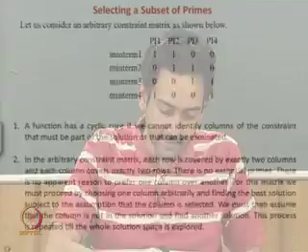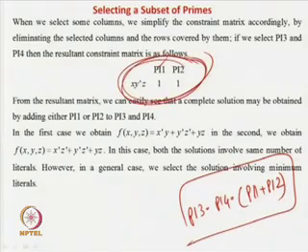But before that we have to do some pre-processing of the matrix, so that the matrix can be made smaller in size if possible. We will try to make the matrix as small as possible. For example, if you have singleton rows, meaning rows with a single 1, then some of the prime implicants have to be selected by default. So you select them and your matrix becomes smaller. Finally, with the remaining matrix we will apply the algorithm to find out if there are choices. Like in this case the final matrix was this small, where you have to take a choice.